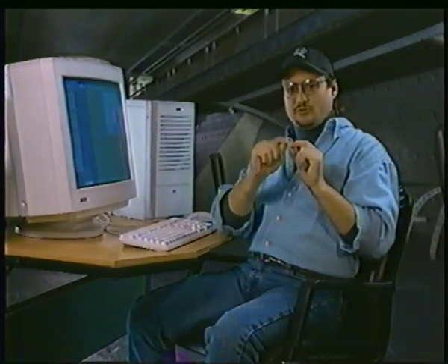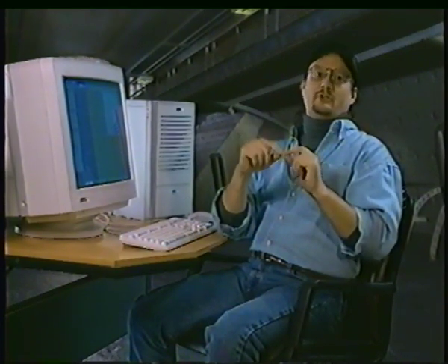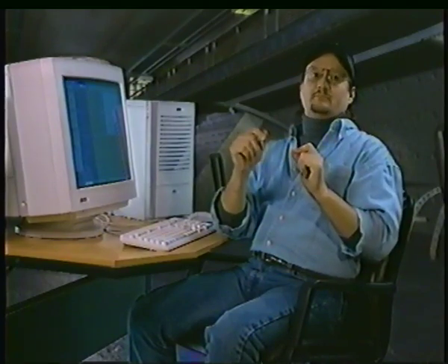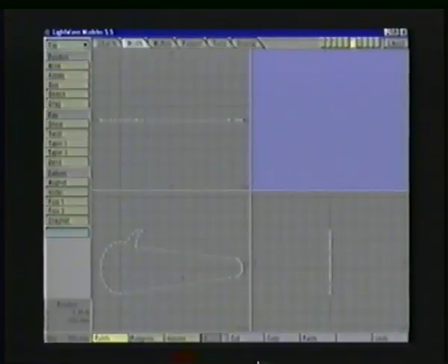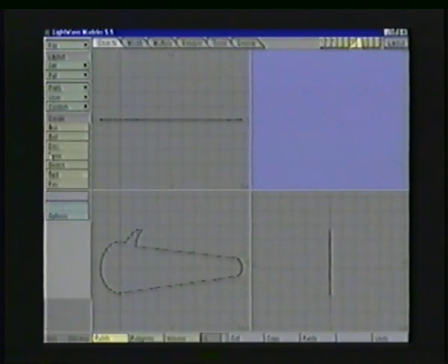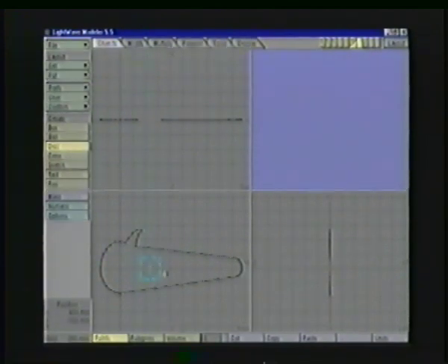It's very difficult to accurately plot points with your point creation tool in a perfect curve, whereas grabbing points directly off of a cylinder or a disc makes it very easy. I'm now going to do the exact same thing in another layer. I'm going to create another disk right here, and I'm basing this on the object in the background. So I'll hit enter to make that disk.